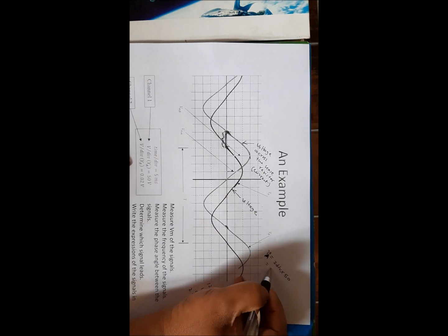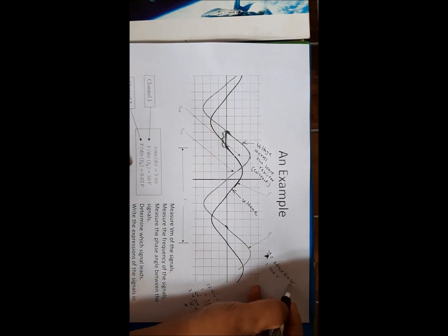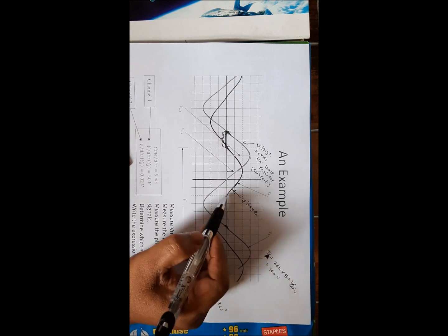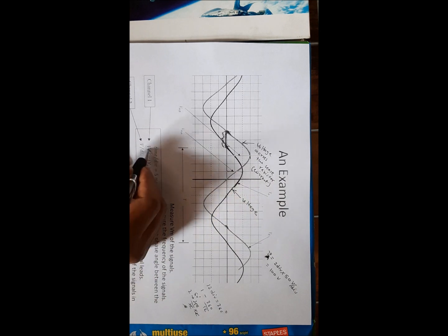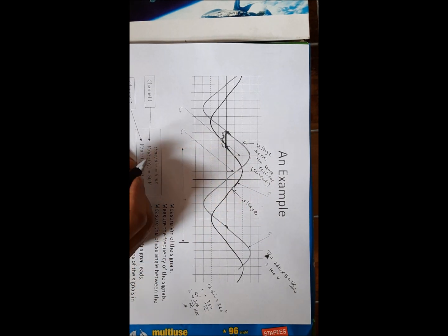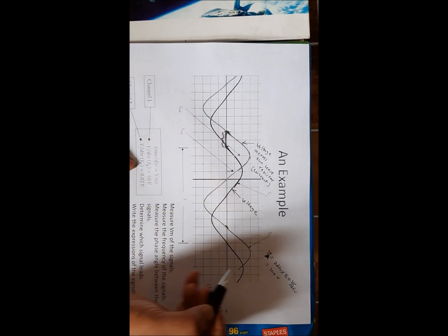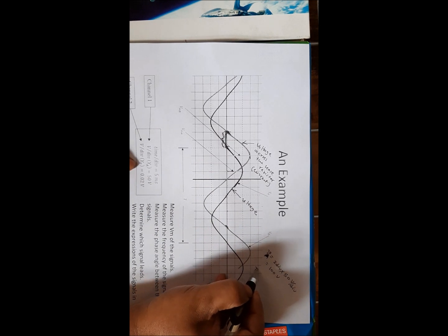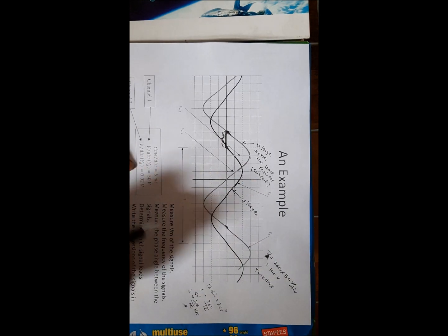So that will be VA equal to 100 volts. So 50 volts per division, you get 100 volts. So the voltage from here to here is 100 volts. Now you have to find the time period. So what is the time period or frequency of this? Here we have 12 divisions, so you can say T equals 12 divisions, and each division has 5 milliseconds.